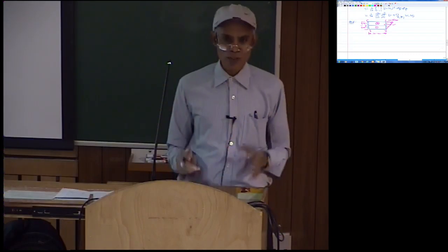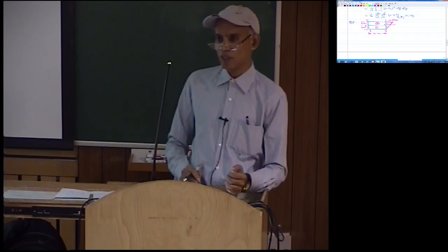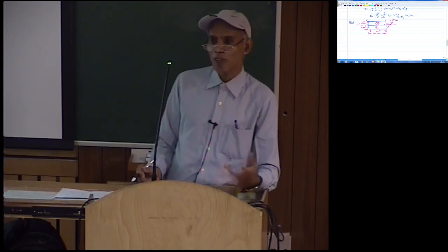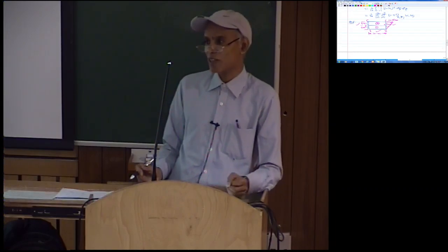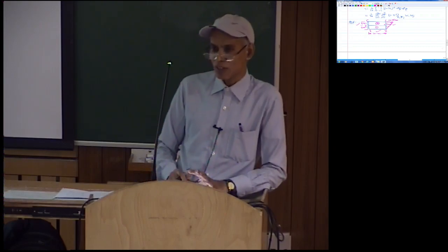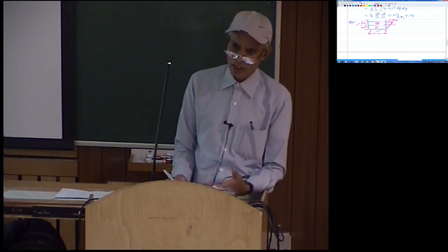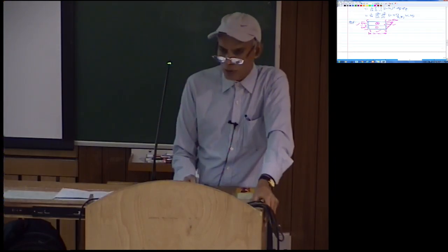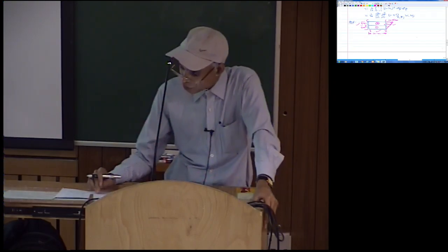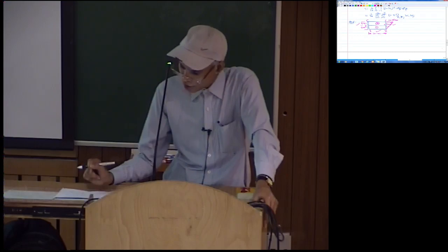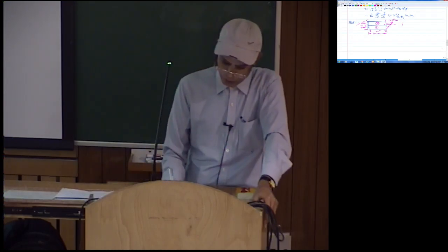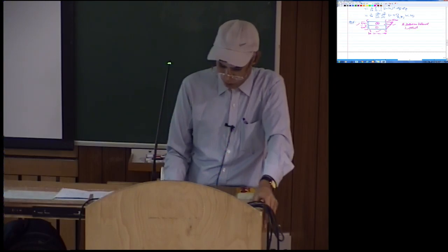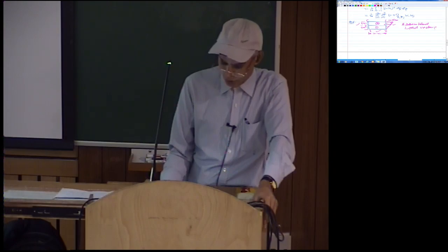Load is in the in-plane direction. The 2 dimensions are comparable. Of course, no mention about the thickness here, but this dimension and this dimension are comparable. So obviously we cannot approximate it as a 1D problem. It has to be taken as a 2D problem, plane stress or plane strain depending on the thickness. But for the purpose of load vector calculation, that doesn't matter. So one is that you have to consider it to be a 2D element, and I have also said that for the finite element mesh of 4 noded isoparametric elements shown, calculate the assembled load vector. So that was the question.